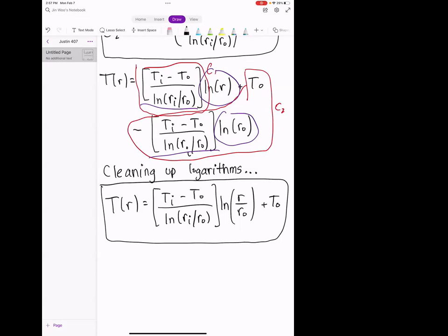That's just another heat equation type problem, and it's very similar to problem 2 on your homework. The biggest difference here is that we're starting out with a different heat equation, because we're starting with the heat equation in cylindrical coordinates. The next step I want to do with this solution is compute the heat transfer rate through this temperature distribution.